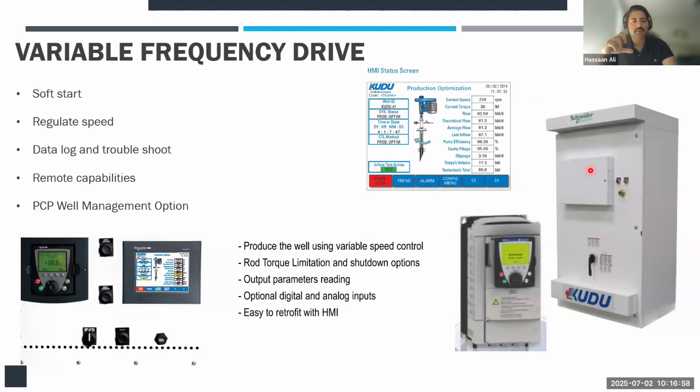And it also helps you to optimize your performance. So if you connect it with a flow gauge, which can be a Venturi type of gauge or impeller type of flow meter, this flow meter can actually send data to your variable frequency drive. You can collect that data, you can optimize it. And in that way, you are always optimizing your well configuration. You can change your RPMs. You can pull your pump, push your pump. You can set it at a deeper depth, things like that.